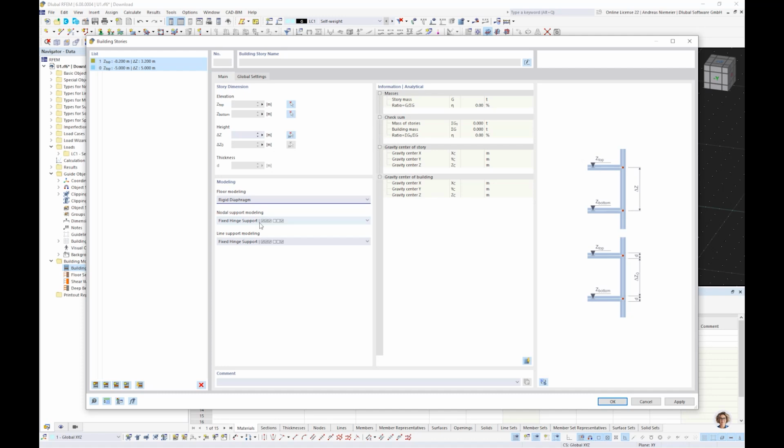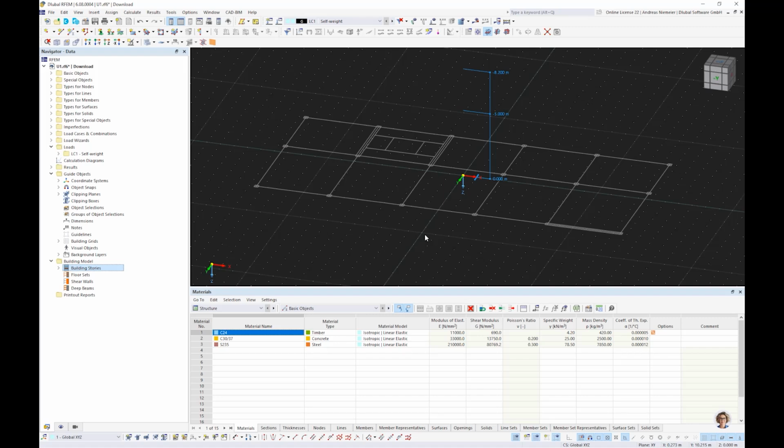Of course you can select something else. Now I confirm, and no blinking and highlighting infos will appear. Only you will see in the middle a dimension that shows us the height of the stories, not more and not less. And now we can start modeling the building.